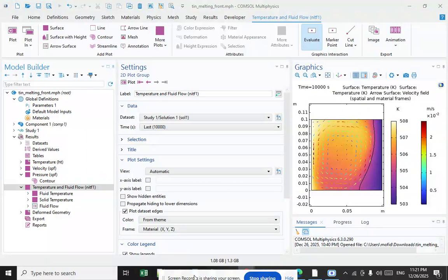While chemically pure compounds exhibit a single temperature melting point between solid and liquid phases, mixtures can either have a single melting point, known as congruent melting, or they have different liquidus and solidus temperatures, resulting in a temperature span where solid and liquid coexist in equilibrium. This is often the case in solid solutions, where the two components are isostructural.